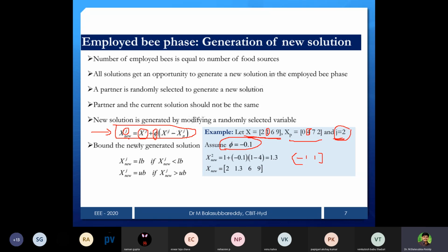Is it valid? You cannot consider that solution, because generator 1 limits are 10 to 150. So the algorithm will say something, and you need to check whether that value is within the limits or not. For that reason we need to check the limits also.